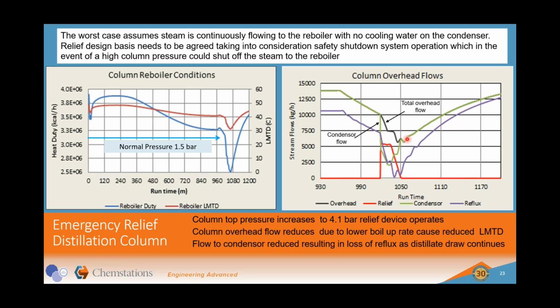And I think the thing to take away from this is that normally, sizing relief valves, you would use maximum heat input to the unit. You would probably take the latent heat of the top and work out a sizing based on that. Now that's basically demonstrated to you that that valve will be oversized. So doing this approach gives you a better understanding of what's taking place in the column during relief.